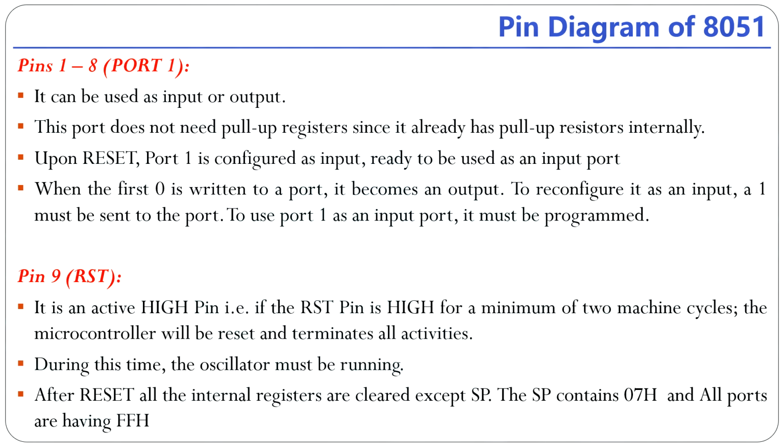That means port 0, port 1, port 2 and port 3. These are the 4 ports available. So these ports have FFH and the stack pointer has 07. So this is the status of the processor after reset operation.